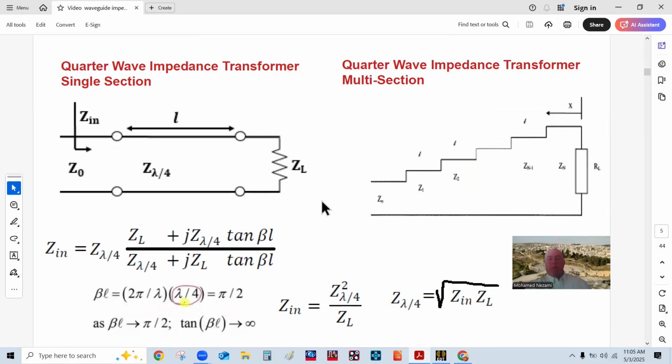Like I said, I did cover the microstrip multi-section quarter wavelength impedance matching transformers in my lecture, and you can find them there. Basically, we use either closed forms, or MATLAB built-in functions, or most commonly, like I'm going to use here in a bit, the tables in Pozar's book.